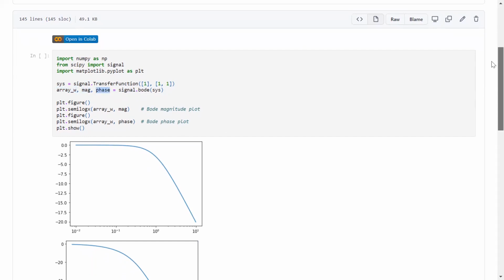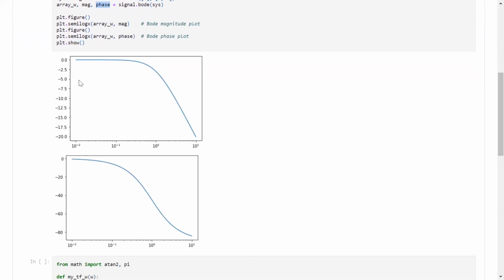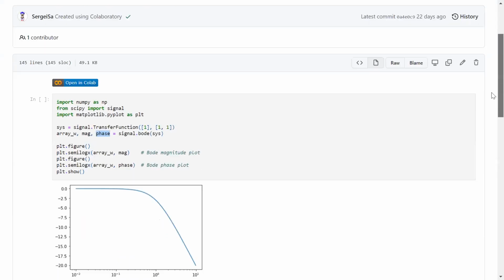You plot it. Notice that here the danger points for magnitude never happen. It never crosses 0. It approaches 0 but never crosses it. So it would never have any problems with that. But the margins might be small. Here again, it never approaches minus 180. So this function is completely stable.